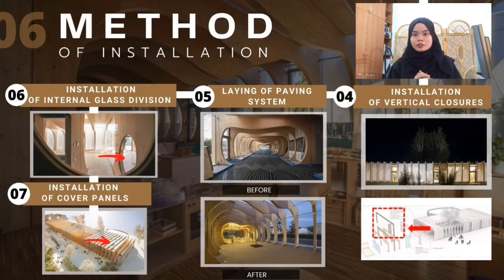When all the important requirements for the structure have been constructed, the next step is to install the paving system. After the paving work is done, only then is the glass division installed. The glass panels should be leveled to ensure that they are standing vertically and that the joints between them are vertical. If the glass panels are in place using self-adhesive partition joints, they can be vertically connected together. Lastly, the cover panels on top of the structure are installed with an opening skylight allowing natural light to pass through the building.